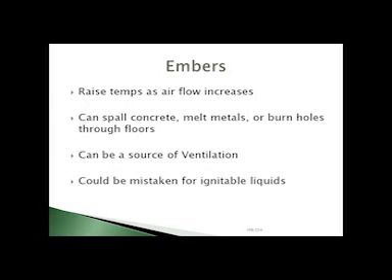So we have embers. Generally they come from your fire, and ventilation has a great effect on these, because anyone who's ever built a fire in their backyard, you get the embers and you blow on them, and it causes a higher heat release rate, and it causes the fire to build. So when the airflow comes from ventilation, it raises the temperature as the airflow increases. And the more airflow, the higher the heat you're going to put out from this.